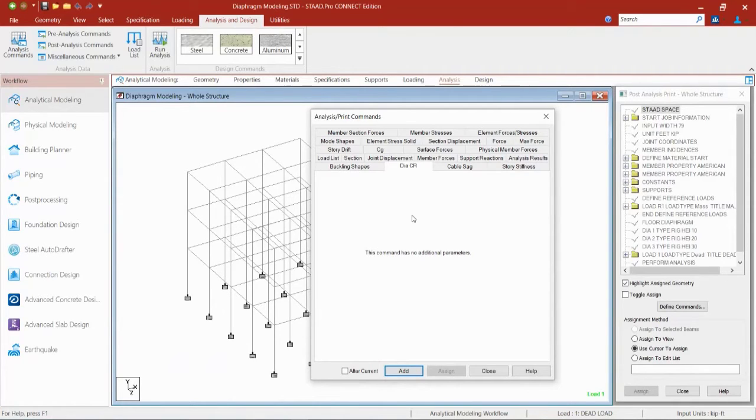So the lateral force at each floor, as generated by earthquake and wind loading, will act at the center of mass of each floor, which is modeled as a rigid floor diaphragm and resisted through the center of rigidity. The center of mass of each floor is defined as the mean location of the mass system of each floor level, and the mass of the floor is assumed to be concentrated at this point when the floor is modeled as a rigid diaphragm. The distance between the center of mass and the center of rigidity will create a lever arm for the natural torsional moment for seismic loads when this option is selected.